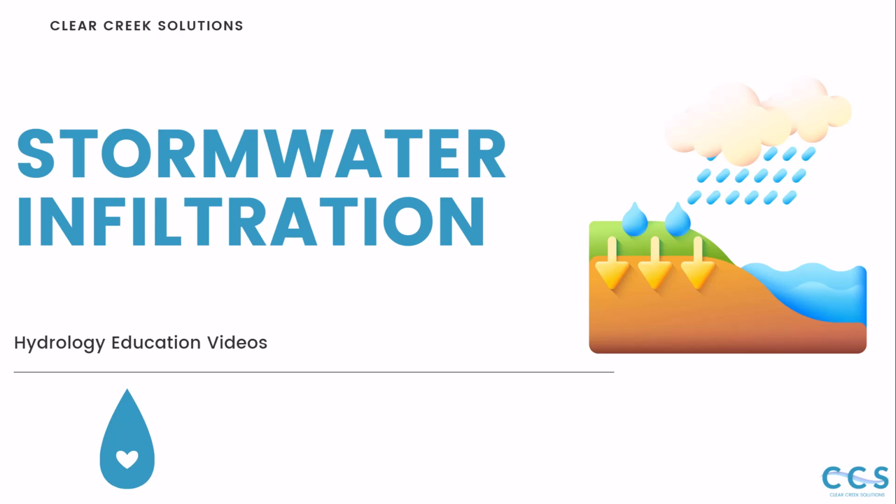Stormwater infiltration is the downward movement of rainfall from the land surface into the soil profile, and is a fundamental hydrologic process that reduces runoff, recharges groundwater, and supports ecosystems. In this video, we'll look at why infiltration matters, the factors that affect it, and how engineers represent it in models such as EPA-SWMM. We'll also highlight three major infiltration methods used in practice: Horton, Green-Ampt, and the NRCS curve number approach.